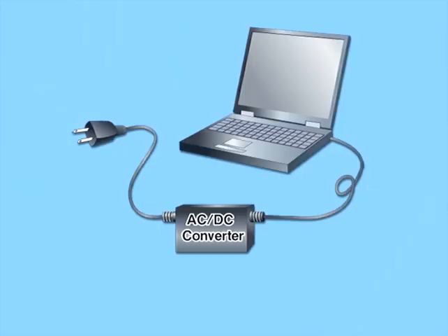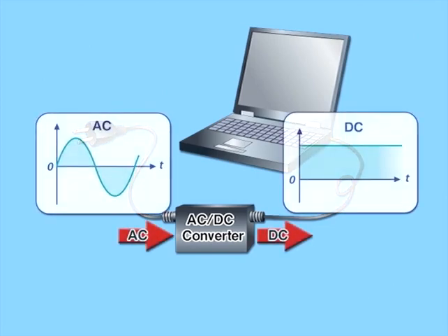The cooling fresh water pump, fluorescent light tube and so on are operated by 60 Hz AC voltage. However, semiconductor devices on control circuit boards and in computers are operated by DC voltage. The circuit that supplies DC power to these semiconductors is an AC-DC converter. Sometimes it is simply called a converter.